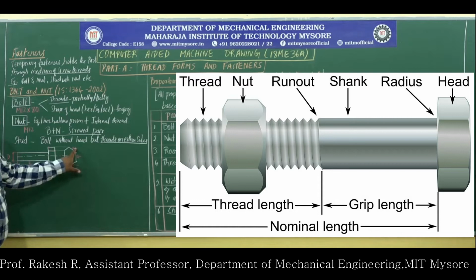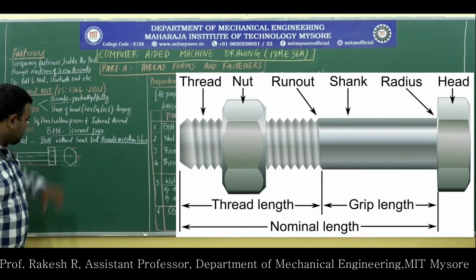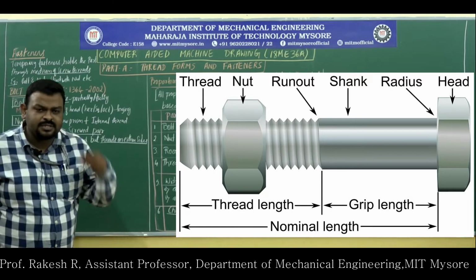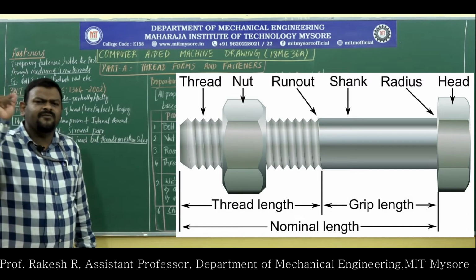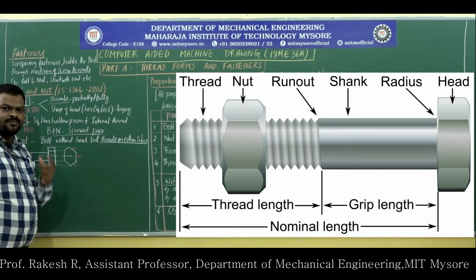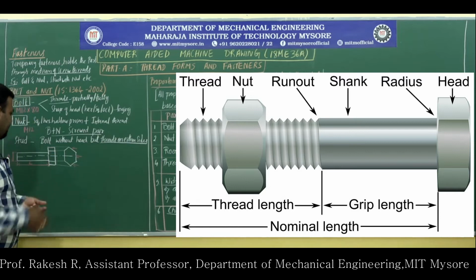So you will see three faces in the front view of the hexagonal side. If you see a top view, you will see only two faces. That is very important. Whenever a drawing is given, always start your drawing with the side view. Got it?